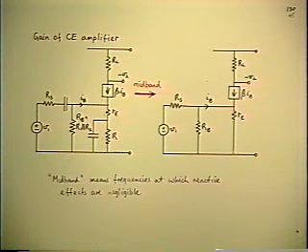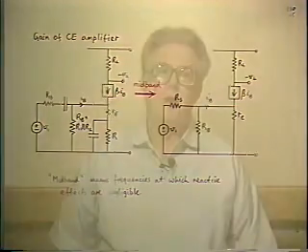That's actually representing the nonlinear exponential current voltage characteristic of the base emitter junction. It's also the reason why this is known as a small signal AC model, because the transistor is basically a nonlinear device. The principal nonlinearity is that base emitter junction, which is an exponential. And as in all nonlinear devices, we try to find a linearized model of it so we can apply all the standard linear analysis techniques.